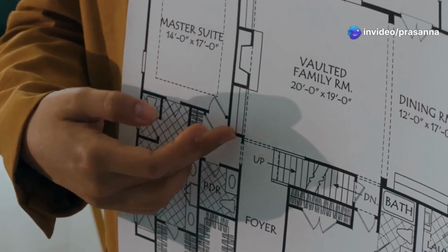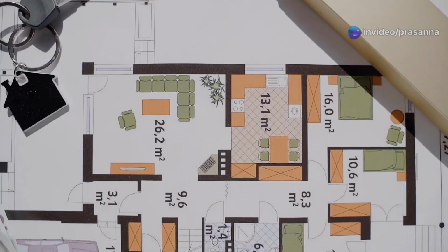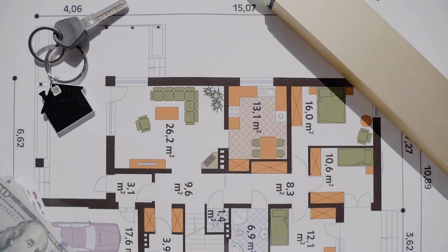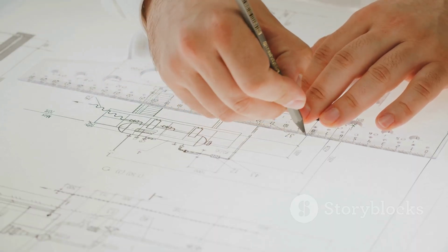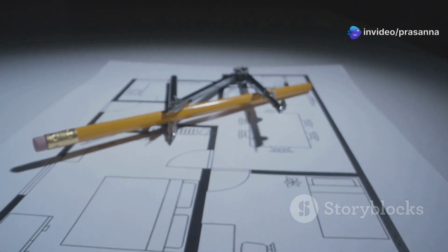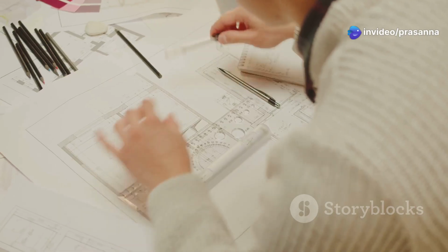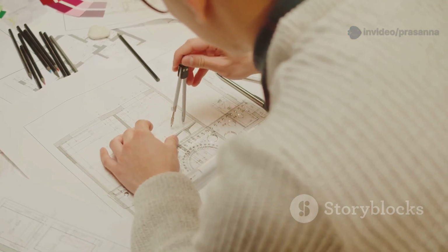Once the AutoCAD plan is imported, it acts as a template. You will see the lines of your floor plan laid out in SketchUp. Now, you can start tracing over these lines using SketchUp's tools. The Line tool and Rectangle tool are very useful here. You will trace the walls first. This will create flat surfaces on top of your imported plan.